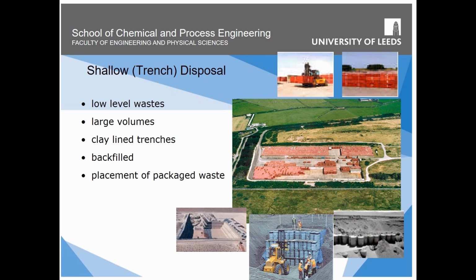And again, we're dealing with relatively short-lived isotopes there. We want to lock that away from the environment for about 200-300 years, and therefore the clay and the material that's used to backfill it is essentially to stop or retard any water getting into the system while the radioactive waste decays.